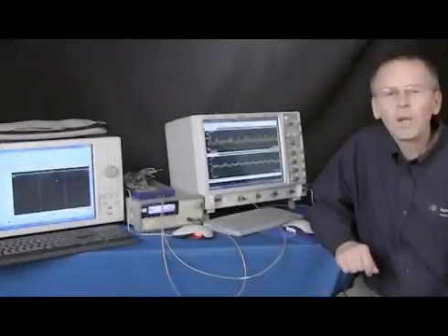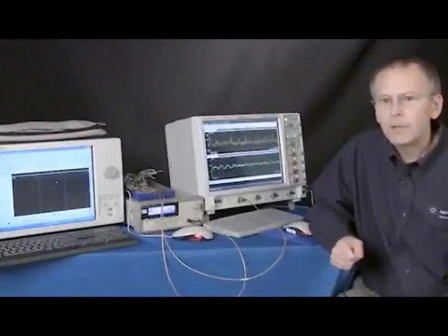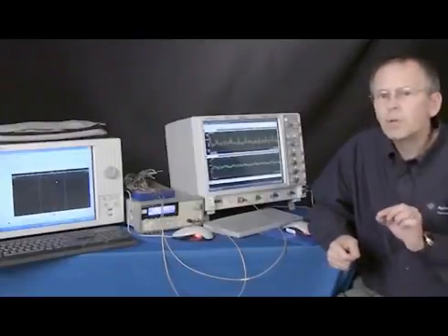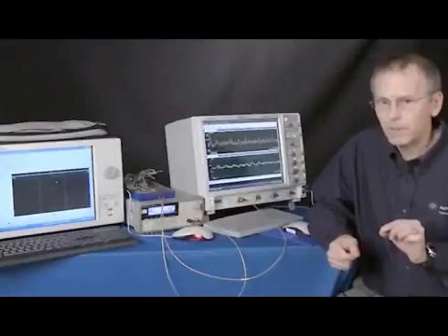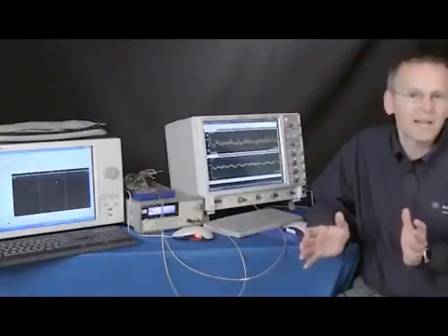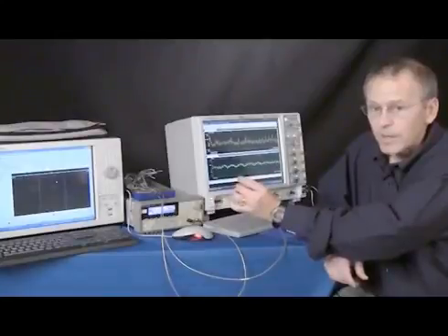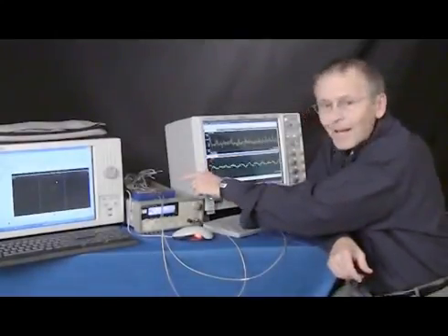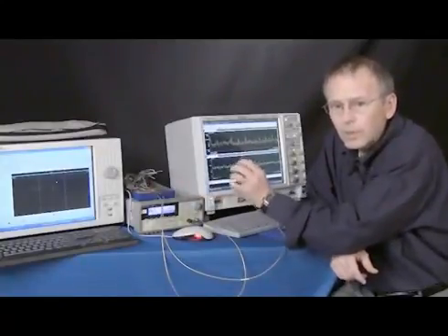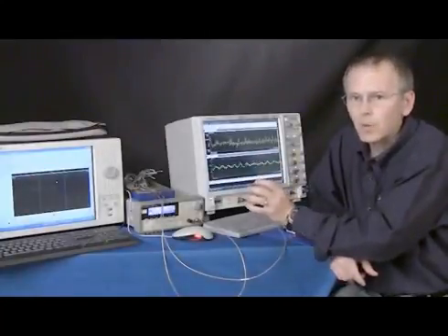What I'd like to do is show you a block diagram of this IQ vector modulator. This was a block diagram created in a tool called System View. And then I want to show you the simulation of that circuit, and we're going to create a golden standard that everything that we measure in our hardware is going to have to be at least as good as. And in the hardware, we're going to take a logic analyzer with VSA running on it, and we're going to probe inside of a Virtex 4 Xilinx FPGA where that IQ vector modulator circuit resides, and we're going to check and see, did it make the standard of that golden standard.